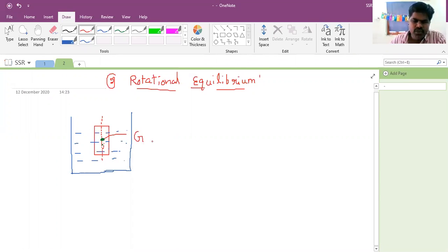Then we have the buoyancy force point also. Force of buoyancy acts vertically up. From the point G, weight acts vertically down. Here, from this point, weight acts like this, mg from point G. And vertically upward we have the upthrust force, or buoyancy force. So like this it will act, the buoyancy force. And at this point FB will act like this. So where is this point? We can expect it below the center of gravity actually.